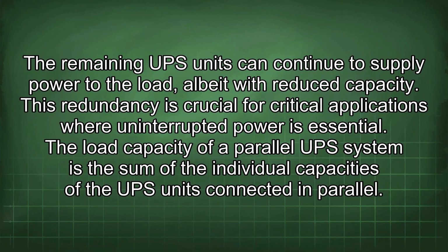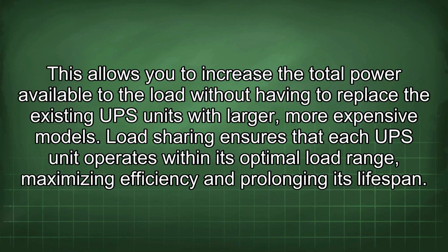The load capacity of a parallel UPS system is the sum of the individual capacities of the UPS units connected in parallel. This allows you to increase the total power available to the load without having to replace the existing UPS units with larger, more expensive models. Load sharing ensures that each UPS unit operates within its optimal load range, maximizing efficiency and prolonging its lifespan.